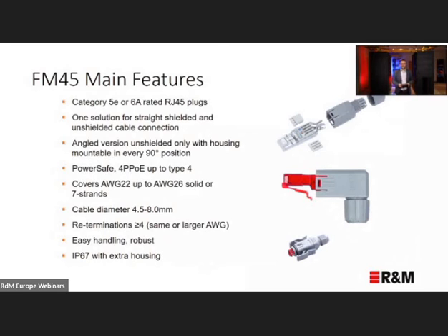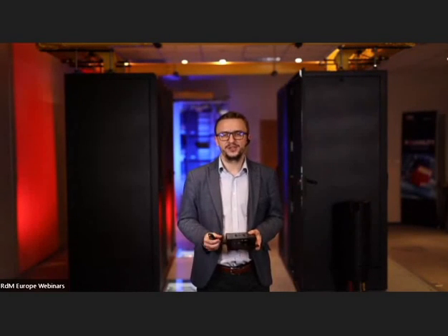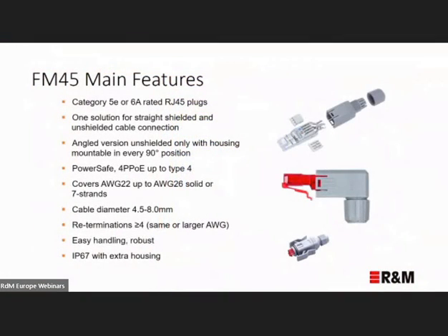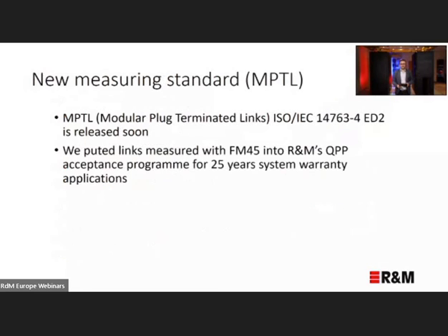The FM45 is also ideal for PoE installations, thanks to IDC termination. That's what I told previously: IDC termination is giving us very good contact. That's why we can use this product for PoE connections up to type 4 of the PoE.